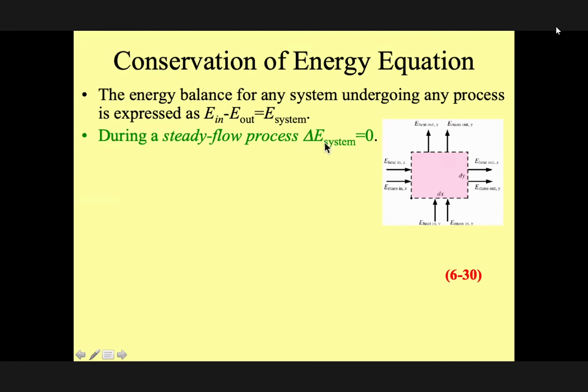This is steady state flow, therefore this term is equal to 0, okay? Therefore, if you look at the energy transfer, there is by heat, by work, as I mentioned, we consider the general term, and also some energy moved by the mass. We try to find each of them separately and take into consideration when we write for this case that you have, okay?